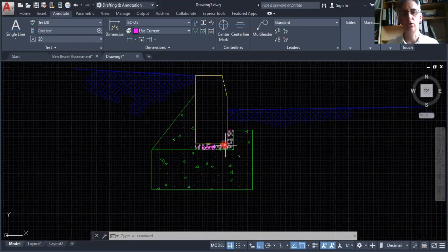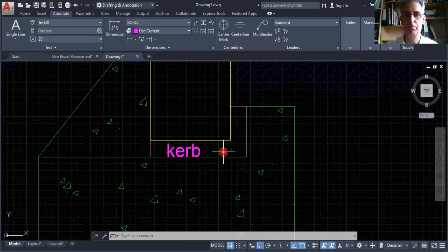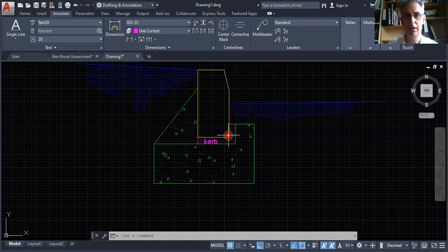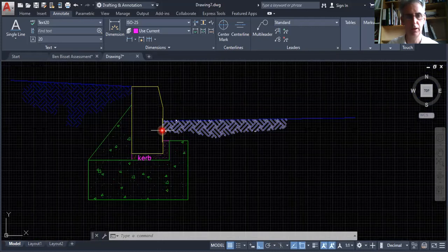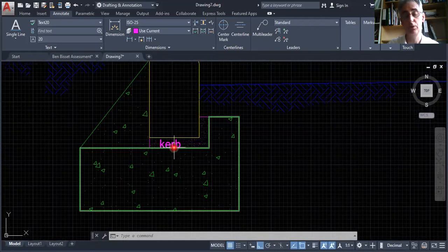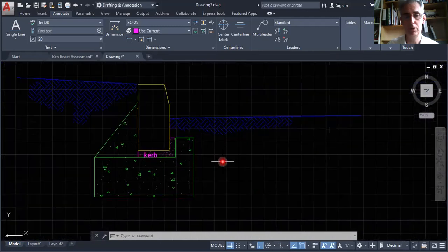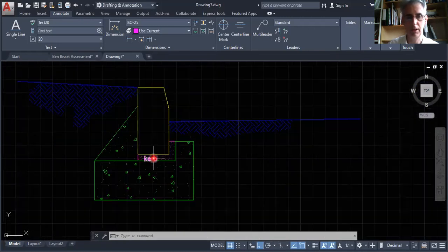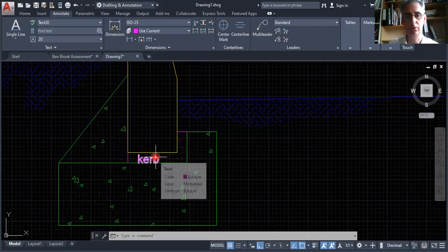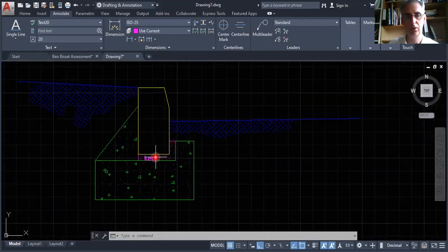So think of it along these lines. Whatever size your drawing is, or if you've got a particular bit of geometry that you know is say 20 or 25, pick the text so that it looks right alongside of that. Obviously, that would be different if this was a big drawing of a house or a factory, because we draw things at 1 to 1 in our model space. We would need to increase the size of our text. The bigger the model, the bigger the text, so I would need to bump this up by 10 times the size, something like that.